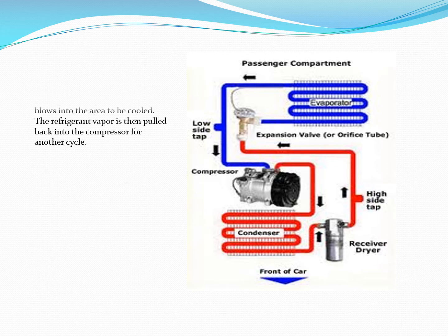Here's another diagram, just another version of it. It's pretty much the same thing. You can see here that you have the compressor, discharge or high pressure side in red, comes out of the compressor into the condenser, through the receiver dryer, through the expansion valve, there's your pressure drop, into the evaporator. Evaporator is going to be cold there, and then it's sucked back into the compressor.